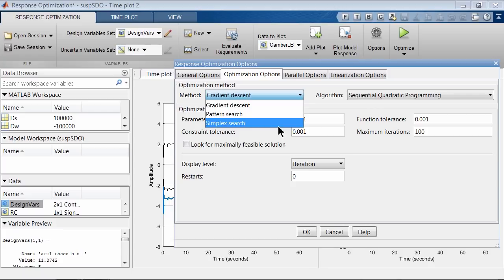Note that both the gradient descent and the simplex search algorithms are local optimization techniques. In other words, these algorithms return only the local minima. For the local optimization algorithms, it is very important to specify a good initial guess for our parameters. Generally, initial guesses are based on design thresholds, domain expertise, etc. Running Monte Carlo type simulations for a range of parameter values is a common way to understand the effect on the model for a given parameter.